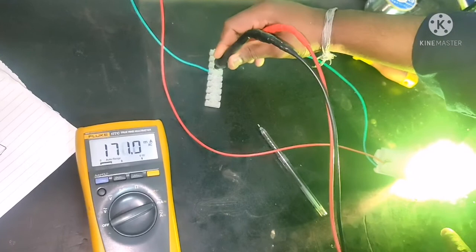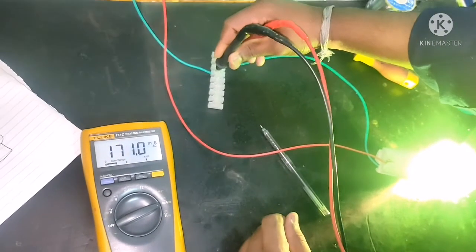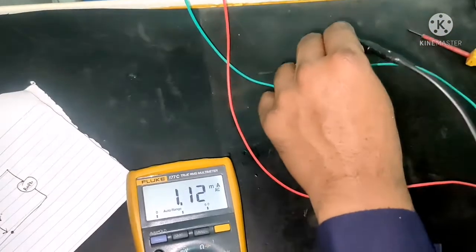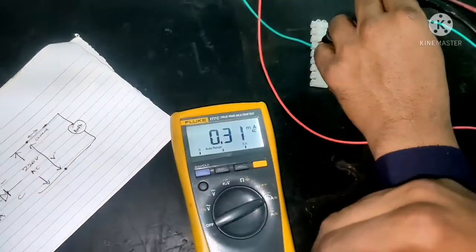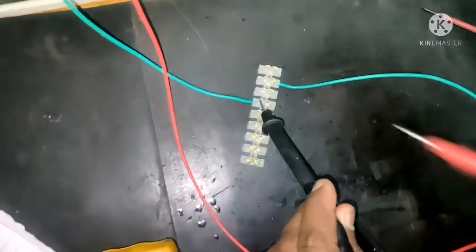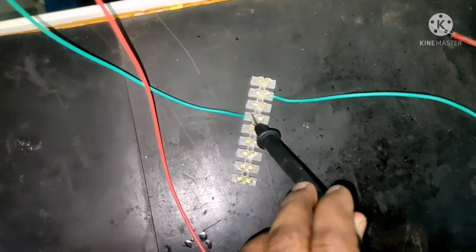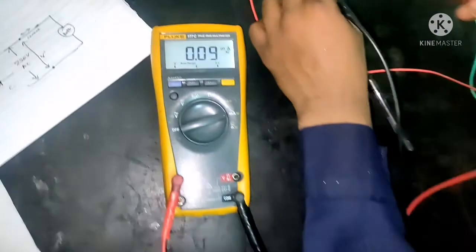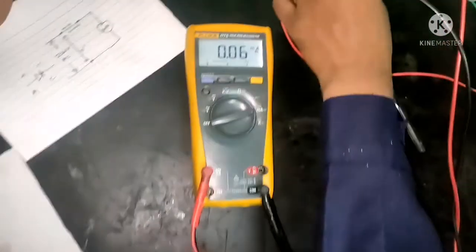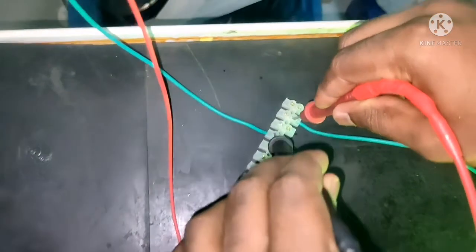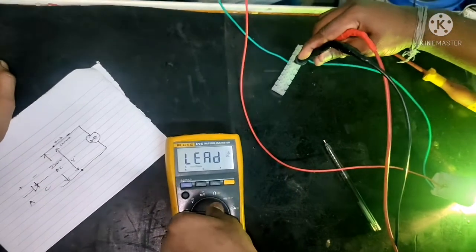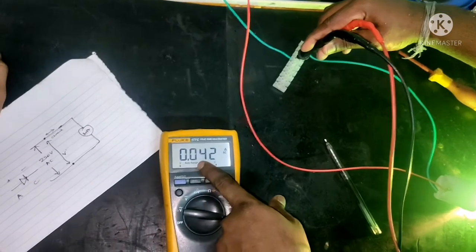Okay, now you can see my leads are on both the wires. That means even though the wire is not in the same line, I have connected the leads on both the wires. That means the current flows from the black cable and passes through the multimeter, and from here it goes to the green line, and then your light is getting on. So if I remove one lead, you can see the light is off. If I put the lead back on the terminal again, you can see the light will glow. So the current is passing through the multimeter and connected to the other end of your wire.